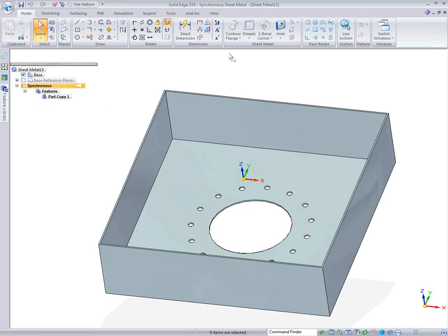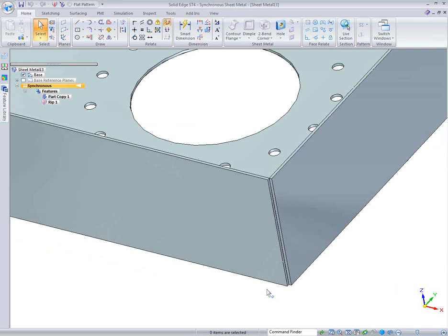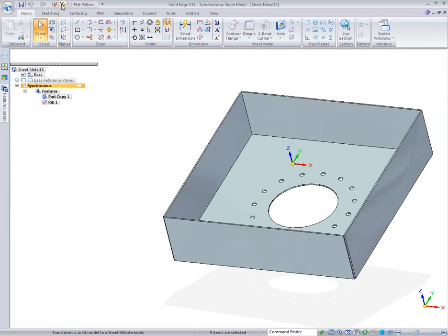What we need, though, is the ability to take this box, whoever made it, and to turn it into Solid Edge sheet metal. Again, very easy to do that. I'm going to go rip the corner. Because this was a box, the corners really weren't ripped. It was just made hollow, but they said, can you make something like this? So we'll go rip those corners, and you can see that I've taken those corners and actually ripped them open that way. And then we'll also just transform this to sheet metal.